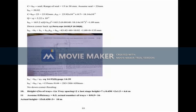We are assuming the actual velocity is 80% of the flooding velocity. The value of psi is equal to 0.07. Substitute, and you will get the value as some 6 gram moles per second. That is also negligible.